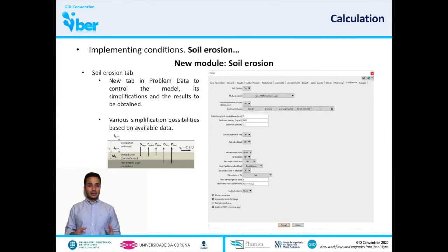Like the Hydrology tab, a tab controls the soil erosion module. Here the user can modify the properties of each sediment class and establish the complexity of the model based on the information available and the results needed as outputs.